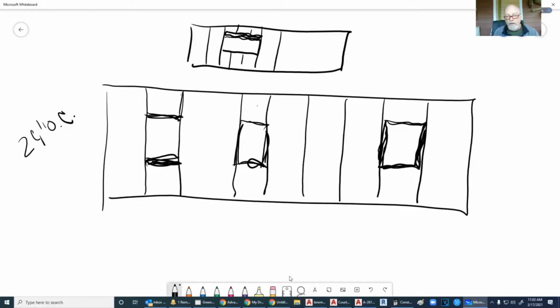Well, a door is going to be obviously bigger, but what we want to do is make sure that we have the placement of that door so at least one side fits in that 2x spacing where we only have to add a stud and eliminate one of the studs that's in there. So, we have to pay real close attention to how we lay out our studs and how we lay out our windows.